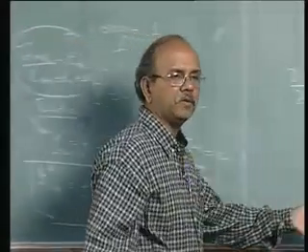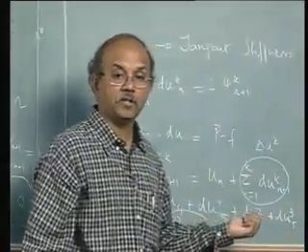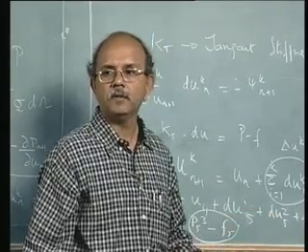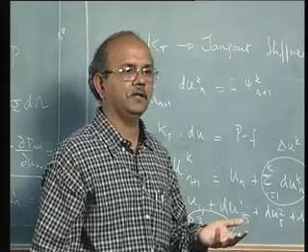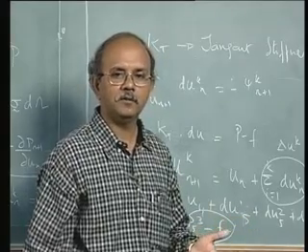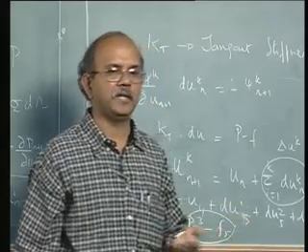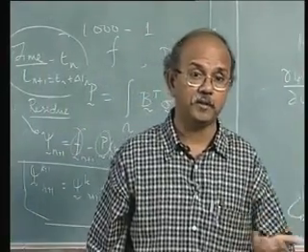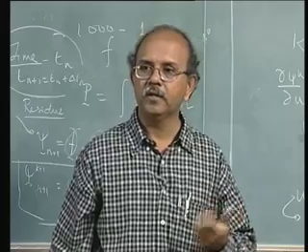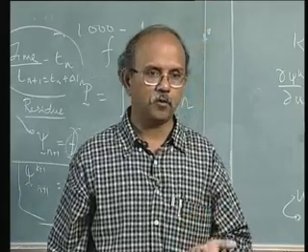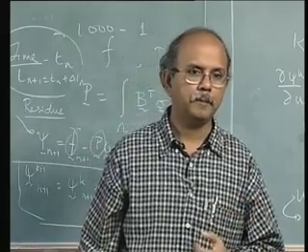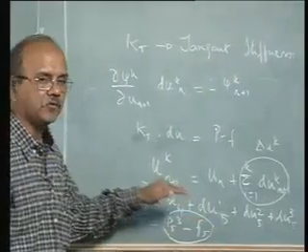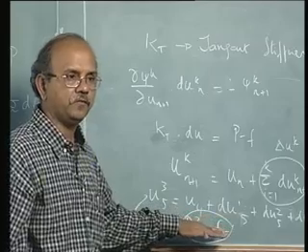Small means it's not 0, but it's a very small quantity. What is small is also important. Suppose I do a problem in Newton meter, the residue may be one value. Suppose I do the same problem in mm, the residue may be another value, and so on. It has to be independent of what you're working on. So you have to be very careful in defining what is small. We'll define that again. Once it's small, we say that convergence has been achieved.